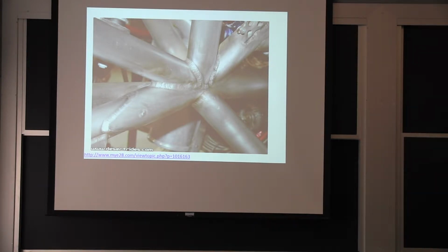If I'm designing a bicycle, aluminum really has its advantages, because for the same weight, I can have something bigger and I can resist the buckling better. So in terms of stiffness performance, even though the aluminum Young's modulus is approximately 3 times less than steel, because you're thinking about buckling and you need a certain thickness, aluminum was a very legitimate choice.